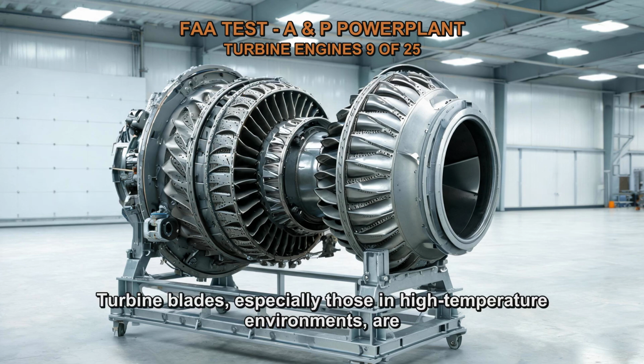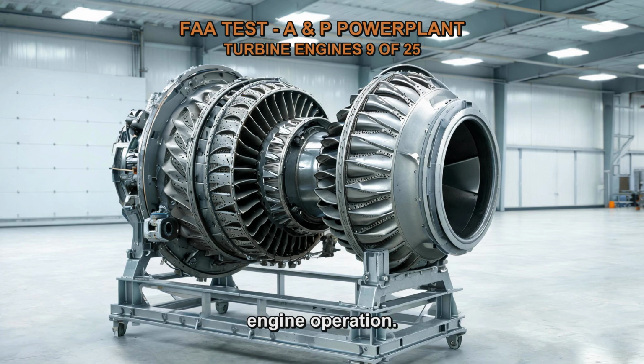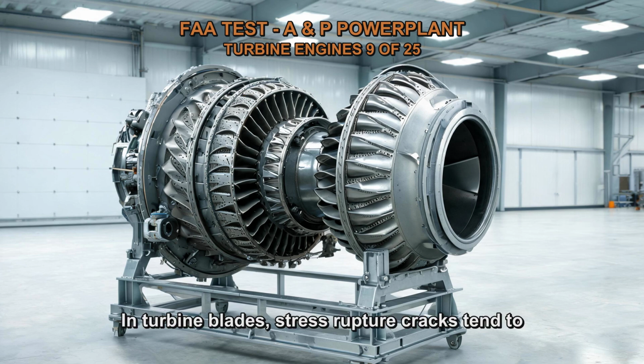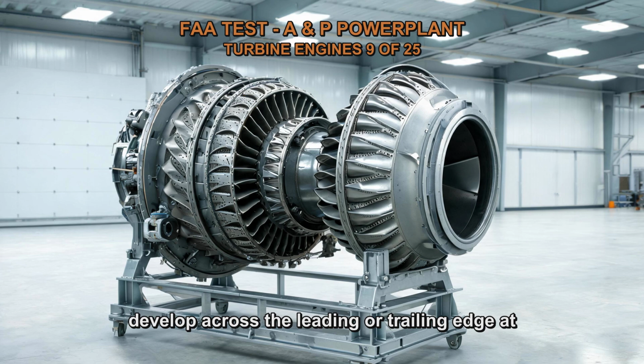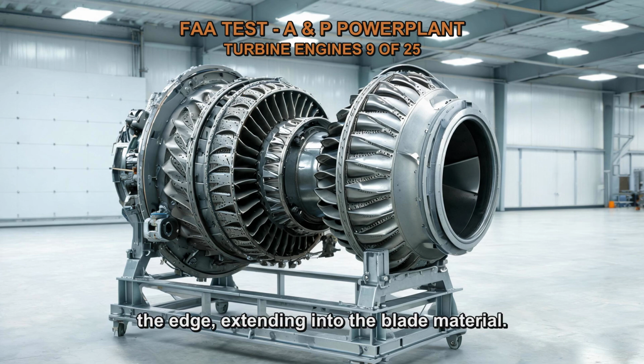Turbine blades, especially those in high-temperature environments, are subjected to significant mechanical and thermal stresses during engine operation. Over time, these stresses can lead to material degradation and the formation of cracks. Stress rupture cracks are a type of crack that occurs due to prolonged exposure to high stress levels. In turbine blades, stress rupture cracks tend to develop across the leading or trailing edge at a right angle to the edge length. These cracks can initiate and propagate perpendicular to the edge, extending into the blade material.